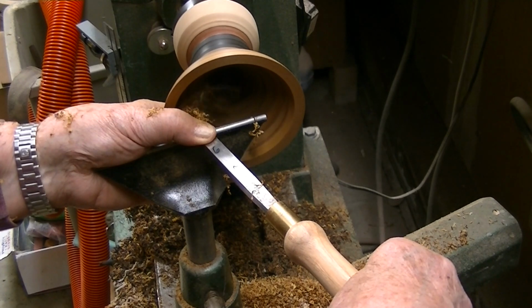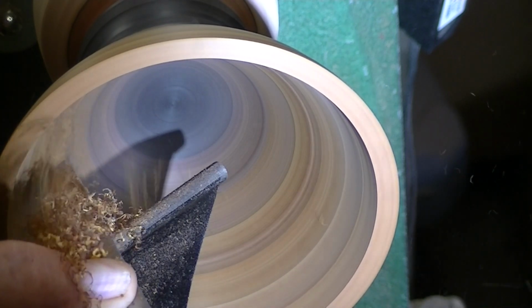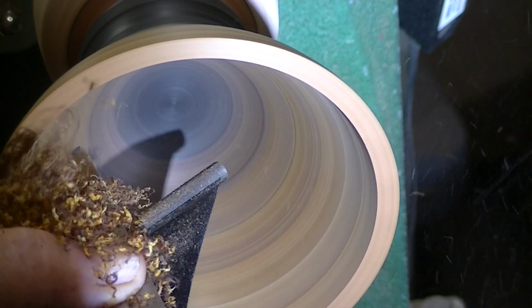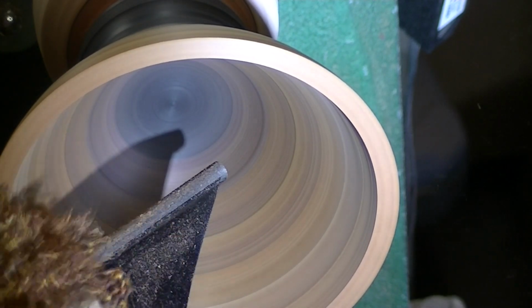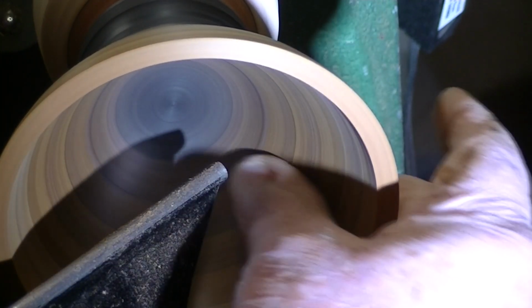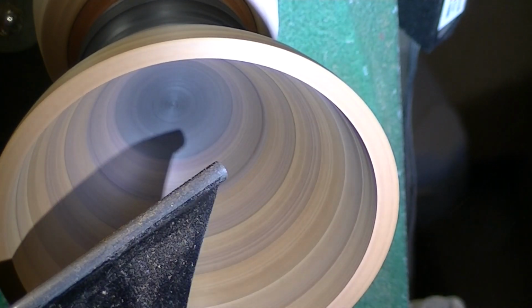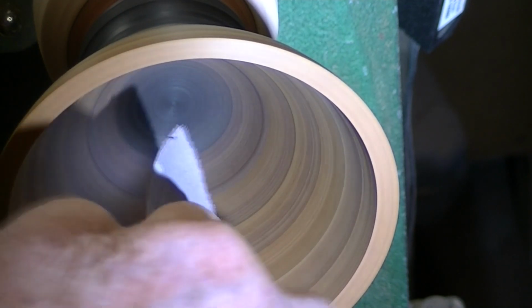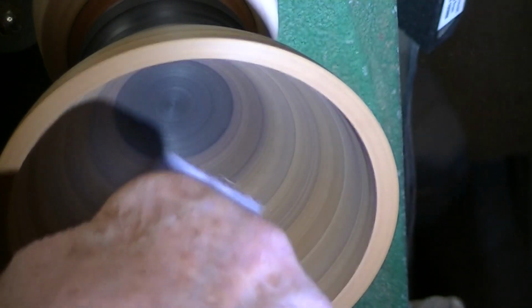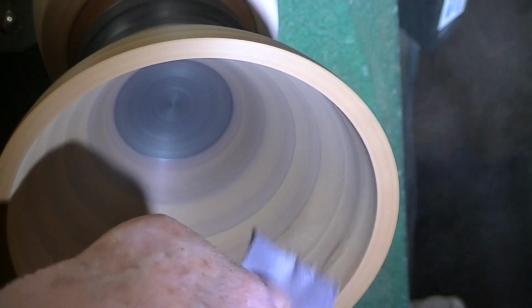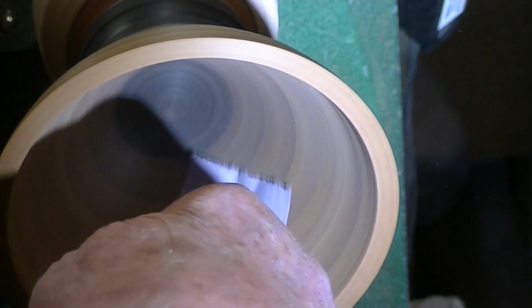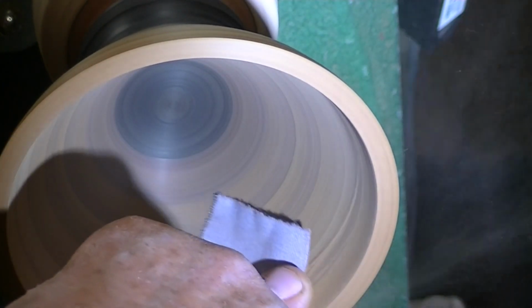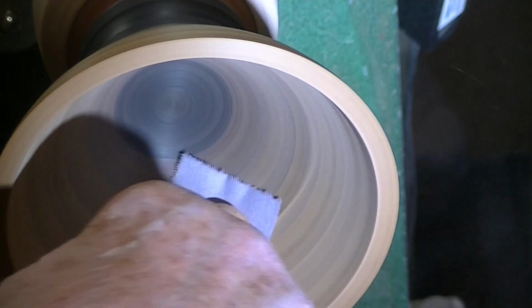I am going to negative rake scrapers that are much more severe in their angles, and you can see the cuts going on inside here. I just wanted you to be able to see how it looks as we begin to clean it up towards the very end. I want that inside to be smooth and perfect. I also want the inside edge wall to be parallel with the exterior wall as best I possibly can. Once I've achieved that, little interior sanding, get it cleaned up inside. And that piece is just about ready to go.